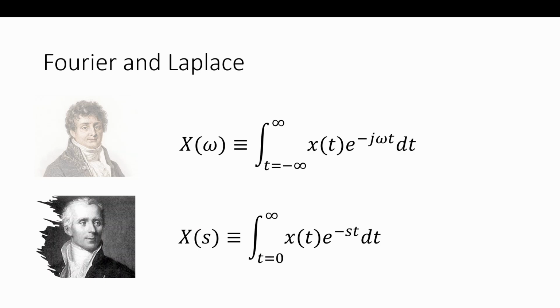That's the Fourier transform. It's like take x of t, and then with lots of computations, the way it's shown here, because we have to set omega to each value, and then, okay, with omega at this particular value, do all this multiply and accumulate or multiply and integrate, and give me the answer and put that one dot on your frequency axis. Now move to the next frequency and move to the next frequency. In the end, we swept all the frequencies and we determined a correlation to each frequency within our waveform. So that's pretty cool. That's the Fourier transform.